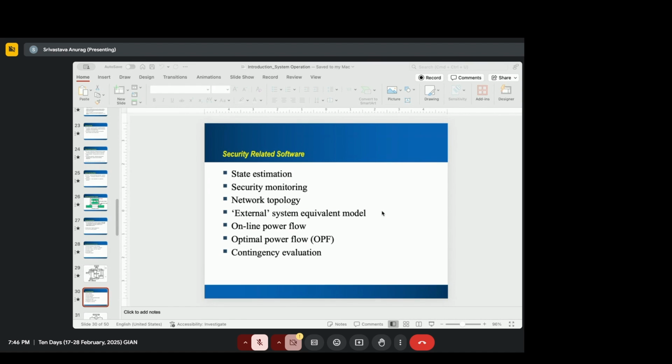So real time depends on two things: the time threshold that we determine, and the setup that we put together to do the simulation, do the data acquisition, do the solution, and produce the result. If you can do this whole process in the time threshold that you put, we'll call it real time, right? So this does not require milliseconds, because if you solve this estimation in milliseconds, it probably will not be right. Why? Because we need to wait for the measurement to be in a steady state.